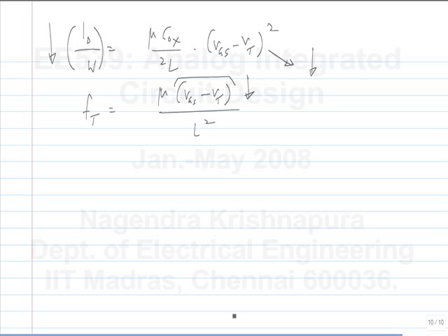So in all cases, whether the load is dominated by external load or internal loads, we saw that the frequency response tends to worsen, meaning the inherent speed of the transistor has to be reduced to get more gain. Okay, that's what we have seen so far. So there is a direct trade-off between the gain that you can get in a given process and the bandwidth that you can get in the same process. Okay.